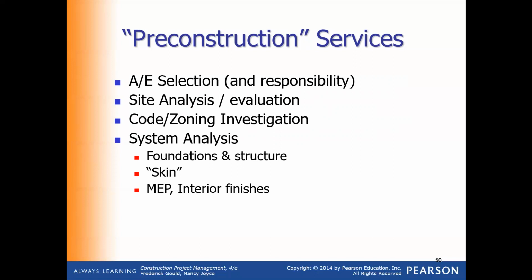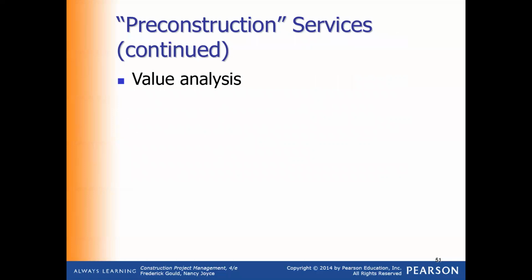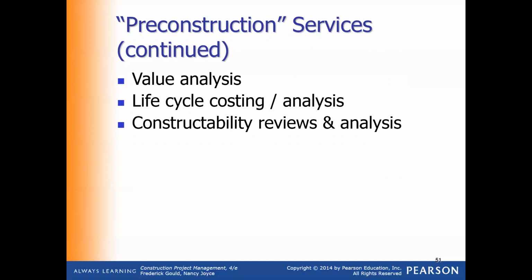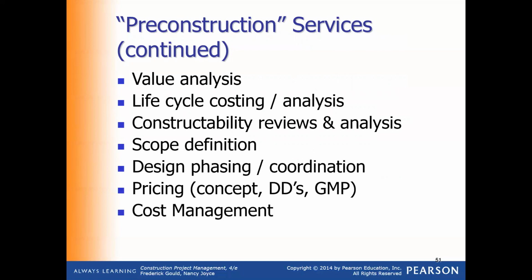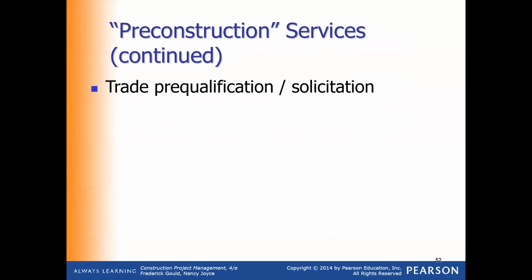Then we do system analysis to determine the type of foundation being built with the recommendation from the PM or the estimator. And then the skin and the MEP, interior and interior finishes and so forth. Then we conduct value engineering, life cycle cost analysis. Then we talked about the constructability reviews and analysis, the scope definition, design phasing and coordination, and the pricing.